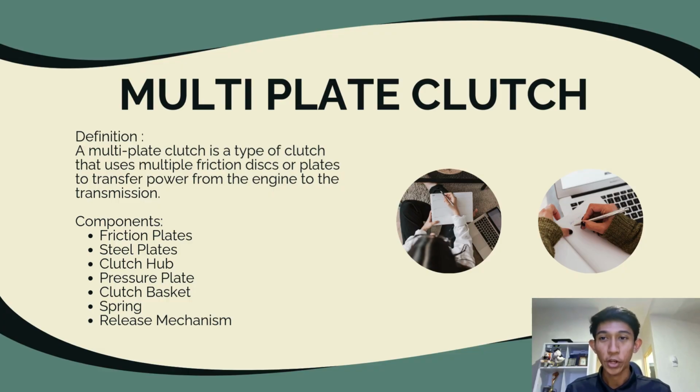Okay, I'll be continuing on the multi-plate clutch. So what is a multi-plate clutch, you might ask? It is a type of clutch that uses multiple friction discs and plates to transfer power from the engine to the transmission. So what does that all do? It provides a high torque transmission capability by increasing the friction surface area, making it ideal for vehicles or even machinery for high power.